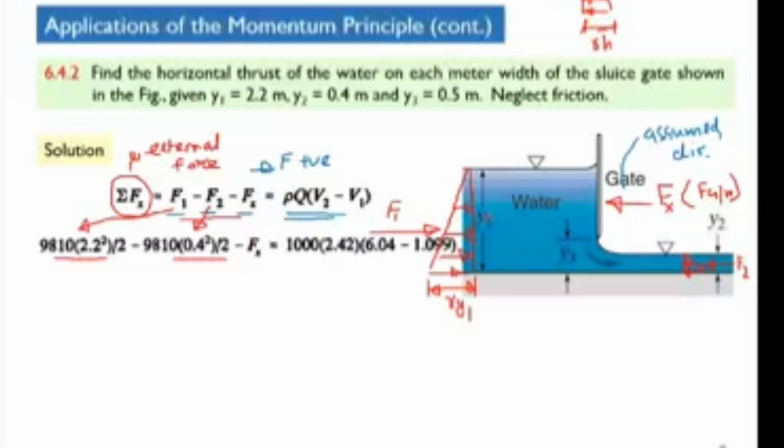And now we also have Y1 here. So what will be this force? It will be the area of this. Clear? And what is the area of this triangle? The area will be equal to half of base into perpendicular. This is Y1 into gamma into Y1, so this will be equal to gamma Y1 square divided by 2.